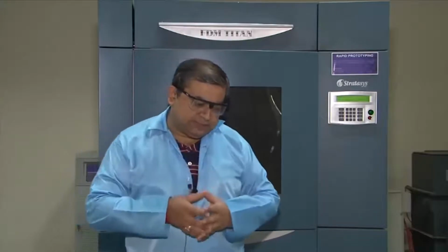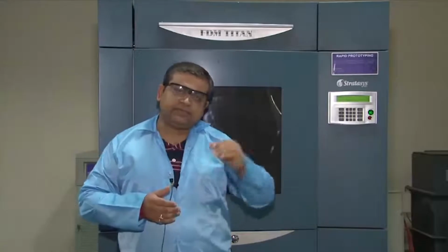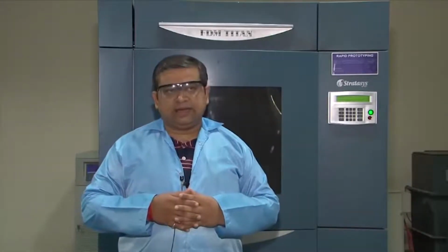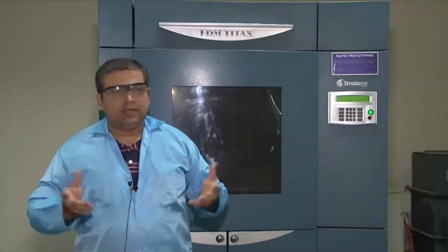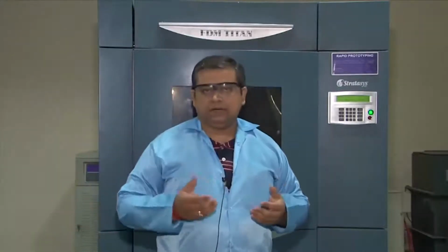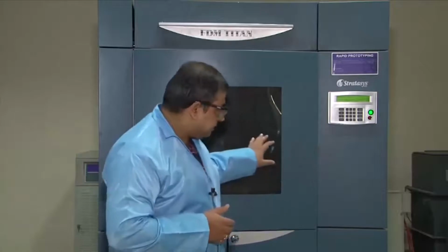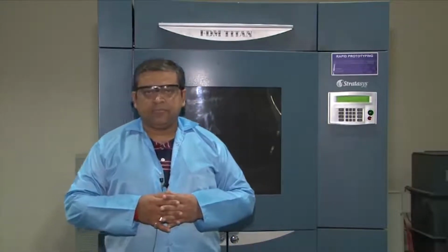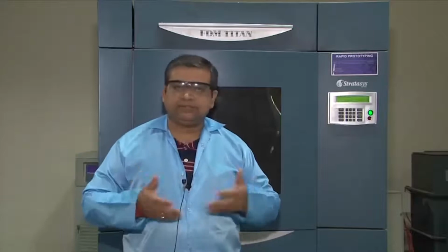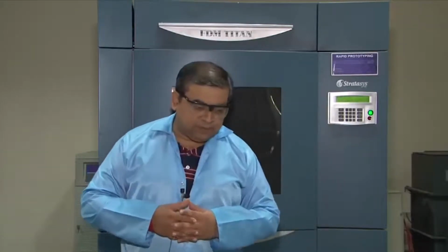Okay, so the advantage behind 3D printing, this area is also known as layered manufacturing because you are manufacturing layer by layer. And the advantage behind such manufacturing processes is typically in terms of the saving of excess material that you otherwise incur in other contact machining processes where there is a lot of waste which is generated in forms of chips, okay, or even in other forming processes or associated, let's say, casting processes which are primary manufacturing processes. There is always a tendency of formulating a layer which is eventually removed. Okay. So in this particular application, the layer deposition process, the advantage is that such savings can happen in terms of obtaining a direct surface finish without performing any other machining process after this process has been done.